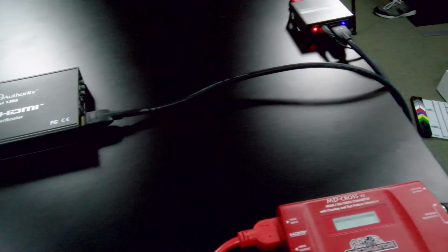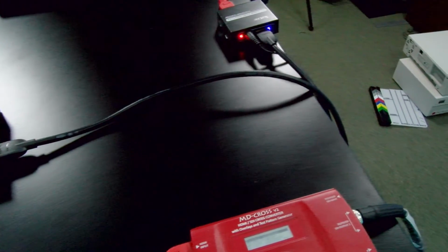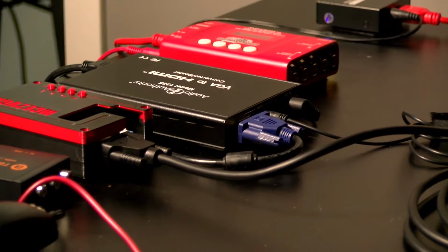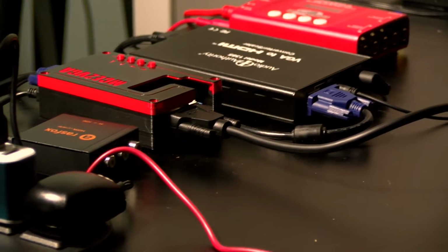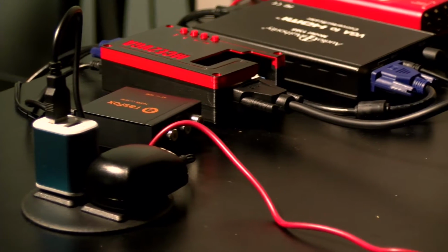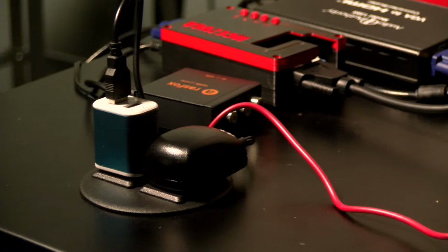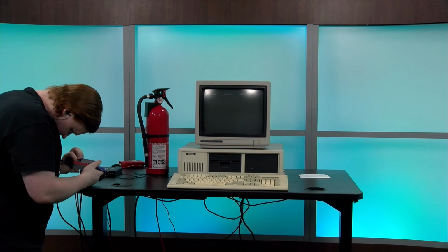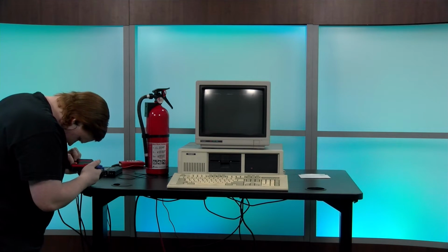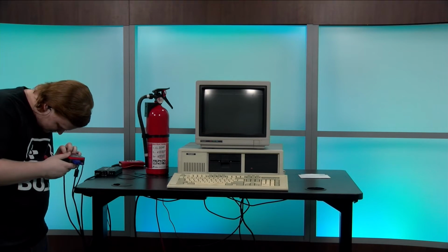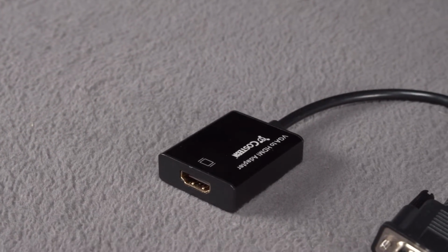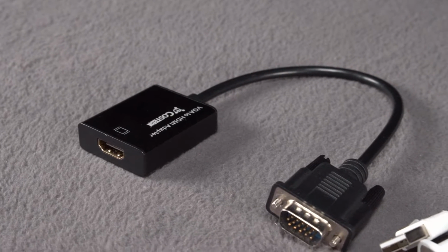We were, however, able to develop what was supposed to be a long single chain of devices into two shorter chains. Both of these smaller chains worked independently but not together from start to finish. With this information, we were able to conclude that our first snag occurred at the VGA to HDMI conversion step. We could convert CGA to VGA and view it on a standard VGA monitor. We could send HDMI to the video hub, as we often do, and send it wherever we wanted. The problem was not with any settings. It was with the devices themselves.